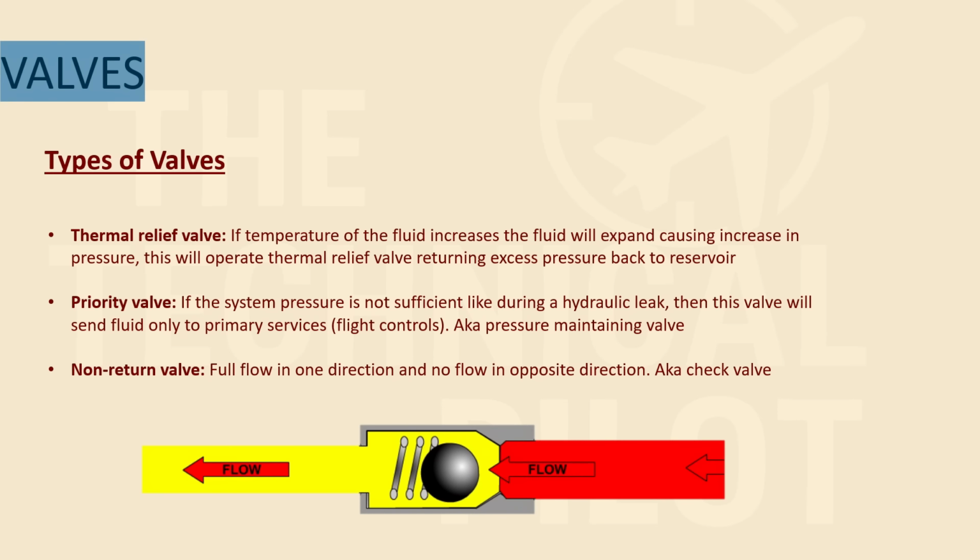And then we have some valves. First is the thermal relief valve. If the temperature of the fluid increases, the fluid will expand, right? This causes an increase in pressure, and the thermal relief valve will open, returning excess fluid back to the reservoir.